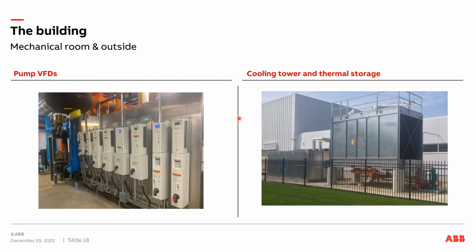I talked about chillers. That's outside. That takes my condenser water and brings that temperature back down. That's what this box is right here with the big fan on top. And here's my waterfall media. So my water is kind of coming down along here. It evaporates and cools down.